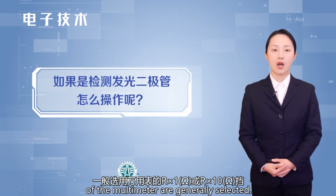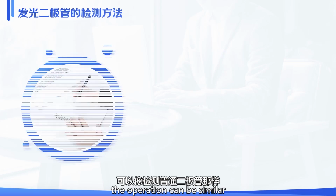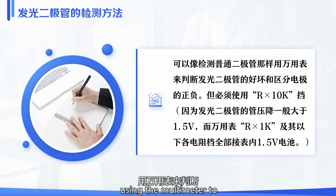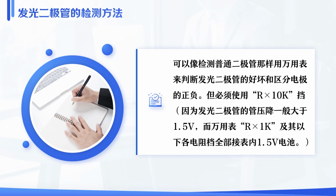generally selected. If detecting light-emitting diodes, the operation can be similar to that for detecting ordinary diodes, using the multimeter to determine the quality and polarity of the LED.